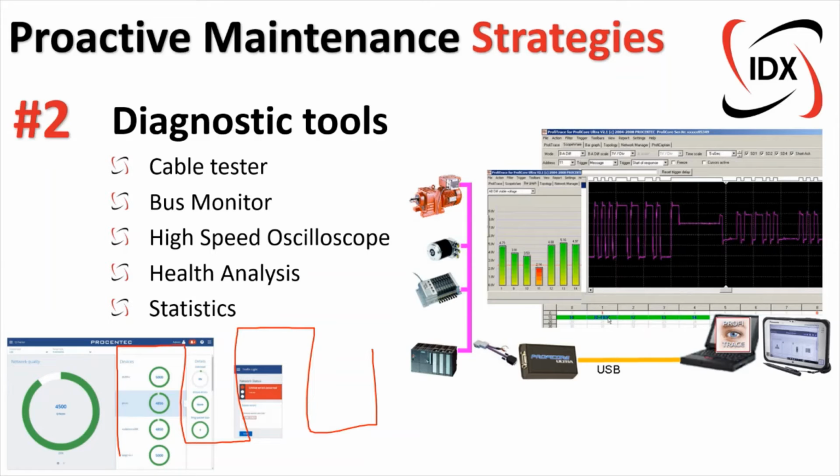Another statistic would be repeats. Repeats is where a PLC tries to communicate with a field device. The field device does not respond after a certain timeout, so the PLC will retry or repeat this telegram to that device. The repeat count can be set in controllers, so you could set it to 3, 4, 5, or even just 1 repeat if you wanted to move on. And the last useful statistic would be something called lost devices. A lost device is where an I/O device is not heard from by the PLC within a certain time period. That's called a watchdog timeout, and then that device will ultimately shut off or go into a safe state, and that's pretty much where plants will start experiencing trips on their network.